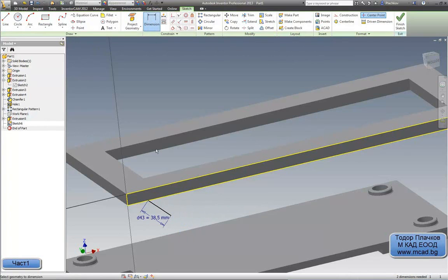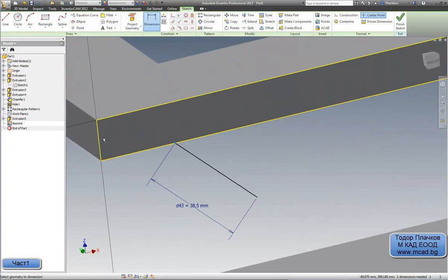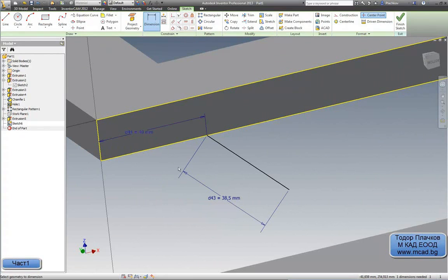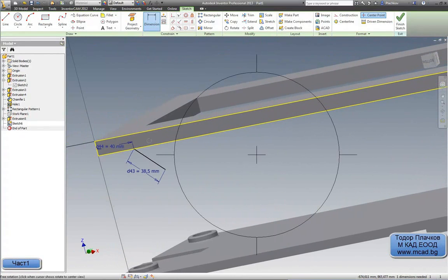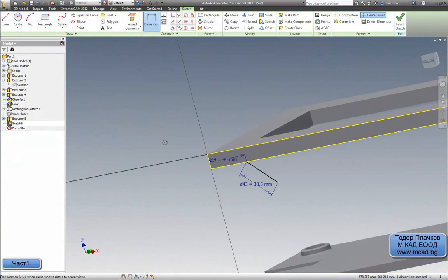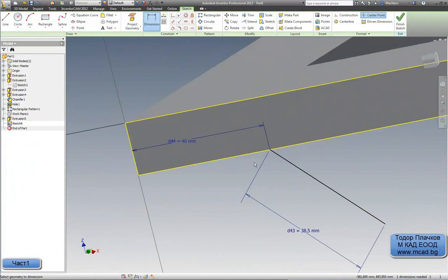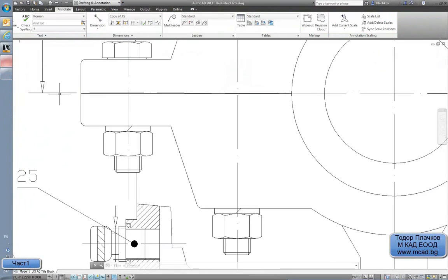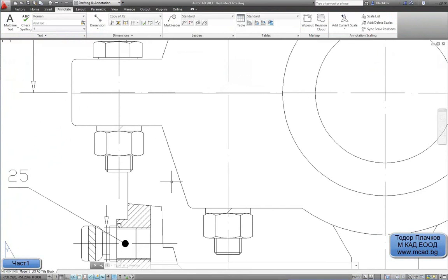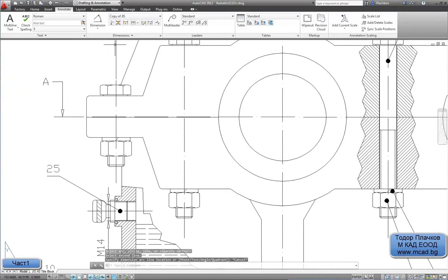I will continue this dimension. If there is projected geometry, you cannot change it in the sketch you are working in right now. When working with a 2D sketch, I suggest using a slightly different visual point, not the normal view, because it's easier to navigate through your part.